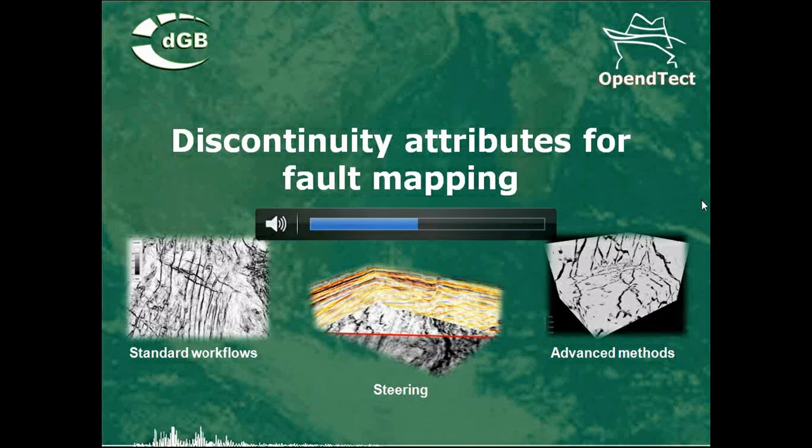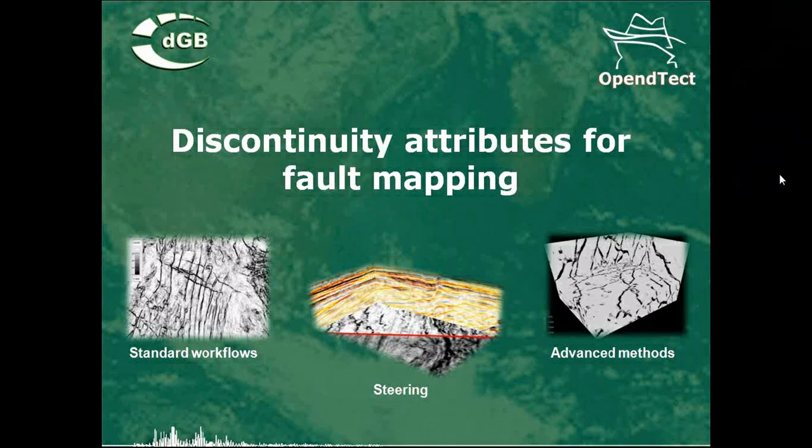Yes, and although the display to time slices is not available, if you have a dense set of 2D lines, it is possible to apply a line set attribute along a 3D interpretation. It will require you to grid the output attribute in order to have a decent display, but it is possible to apply 2D data along a 3D interpretation.